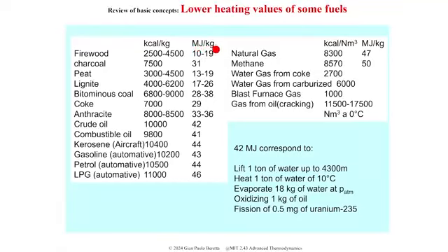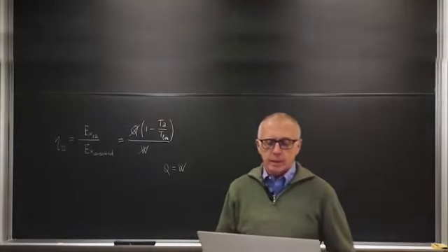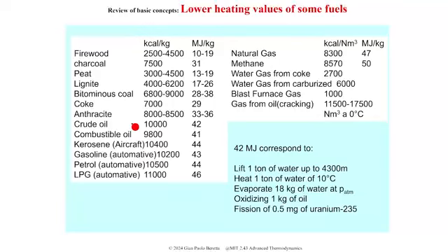This is megajoules per kilogram. And you see that when you present them in terms of these units per kilogram, the fuels have definitely different heating values, but they are within a limited range. They're all around 40. 42 is crude oil. I mean, a typical value, because crude oil varies a lot from place to place, but the canonical standard is 42 megajoules.